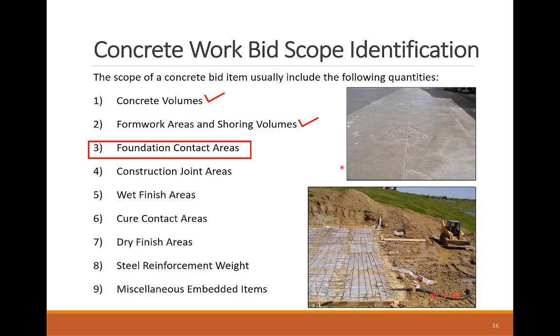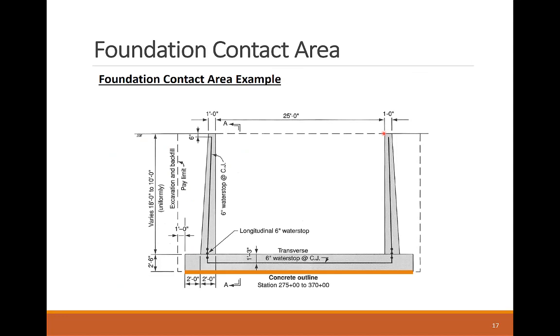Also, finishing the soil before placing the concrete is helpful to avoid settlements at some spots below the concrete structure, especially when dealing with high traffic sidewalks. For the drainage channel, the soil contact area is the width of the slab times the length of the channel.